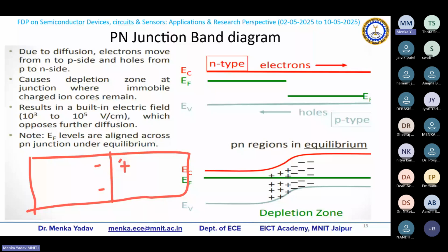What we know, if on one side negative charged ions are there and on the other side positive charged ions are there, we can consider that this is going to form just like a capacitor. Can I say it like that? So basically from this to this is the region which is depleted of the charge carriers. In order to see the statics inside this, the details, you can go with the Poisson's equation. You can just solve it and you will find that the electric field in this particular region is going to take place in this way.